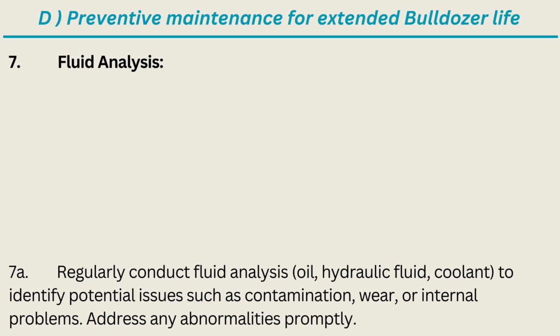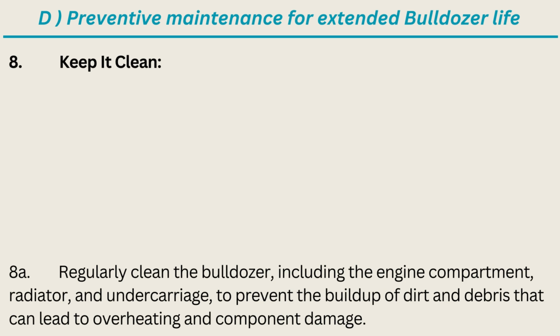7. Fluid analysis. 7A. Regularly conduct fluid analysis of oil, hydraulic fluid, and coolant to identify potential issues such as contamination, wear, or internal problems. Address any abnormalities promptly. 8. Keep it clean. 8A. Regularly clean the bulldozer, including the engine compartment, radiator, and undercarriage, to prevent the buildup of dirt and debris that can lead to overheating and component damage.